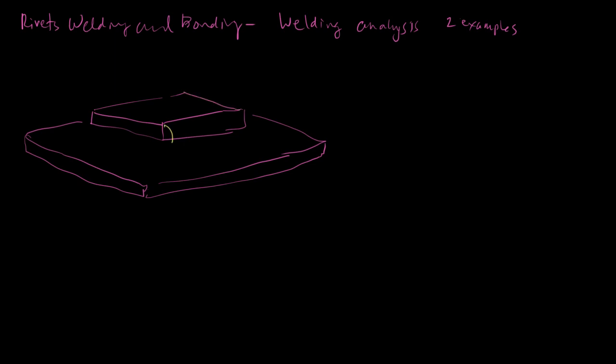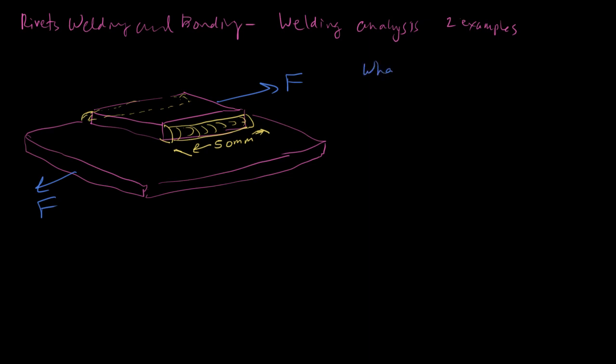If I have a fillet weld here on each side of this plate and the same type of weld all the way on the back side of the plate, and I know that this distance here is 50 millimeters, the question is, what is the max force, or what is the force F, that can be sustained